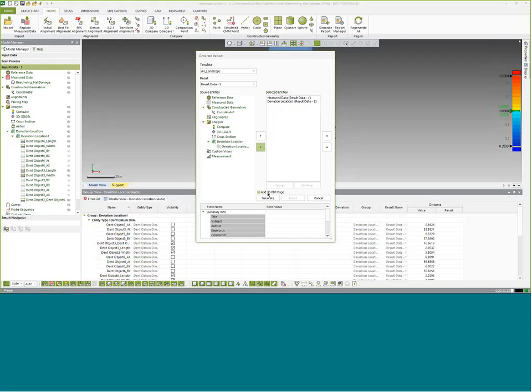One of the cool things about the reporting is if I do a 3D PDF page on the report, this stuff will come in and you will be able to open that in Acrobat, spin it around, look at the color map, see the part, and then the functionality is in the Acrobat PDF document where you can actually turn the tags off and on and things like that. So that's really great to be able to send someone if they need to check out some analysis, or you're just sharing something even internally. They don't have access to the program.